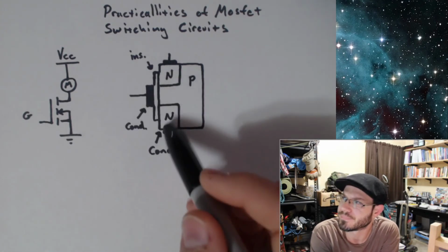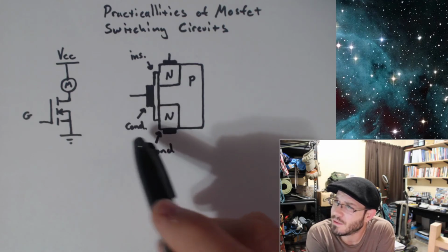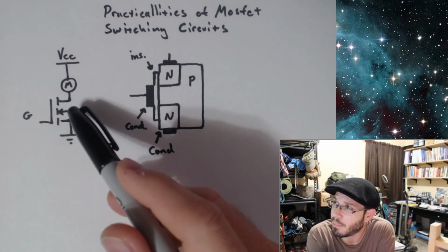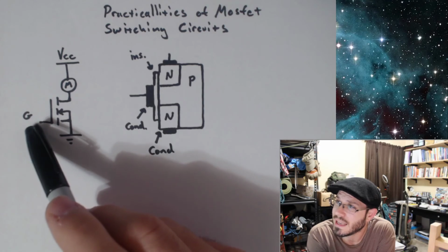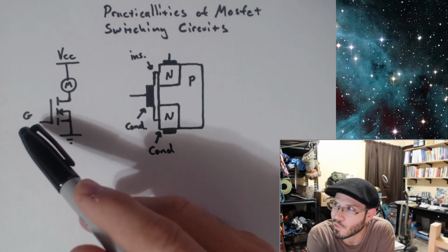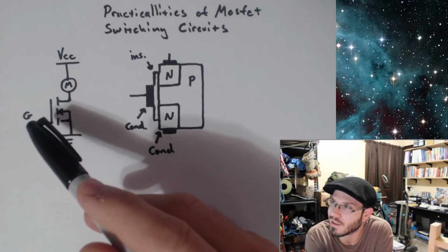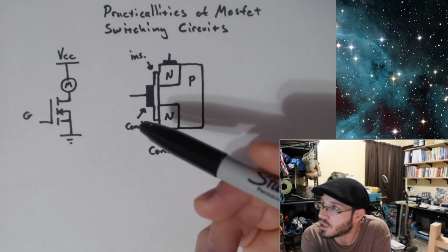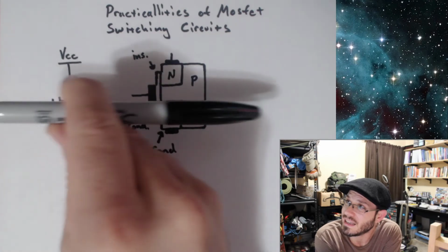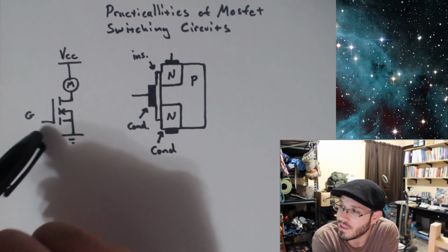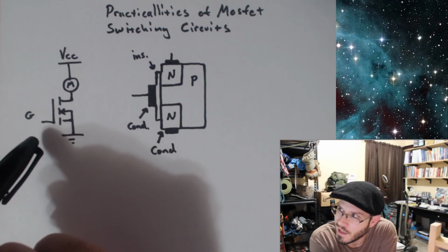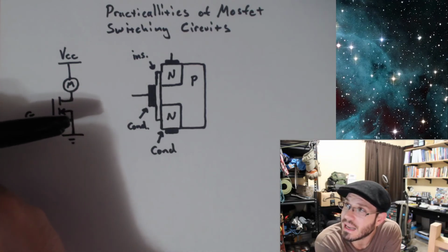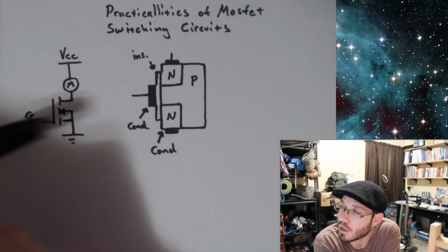And then we'll build upon that. So one of the first things I want to draw your attention to is when you have a MOSFET in an application like this, you're controlling the gate with a digital logic signal, 0 volts or 5 volts. You're turning this guy on and off, essentially. Now, the benefit of a MOSFET as opposed to a BJT is less current going into the device, right? So as far as driving this from a logic signal, you can count on a very high impedance. So we can be guaranteed that we will not use very much current going into the device.